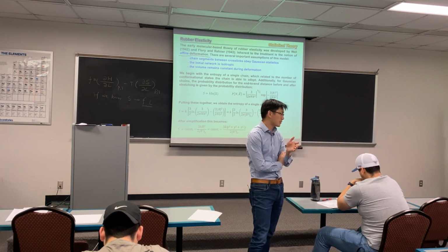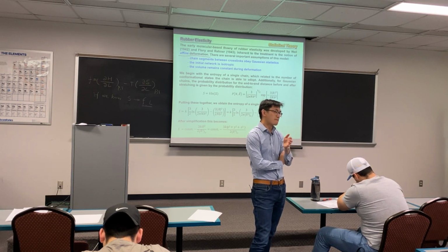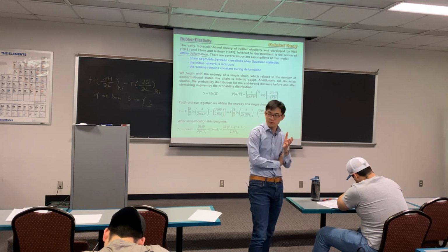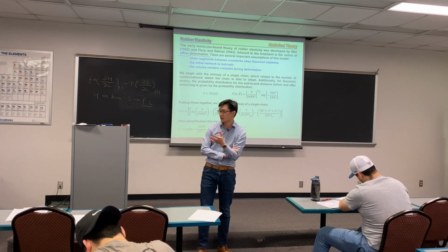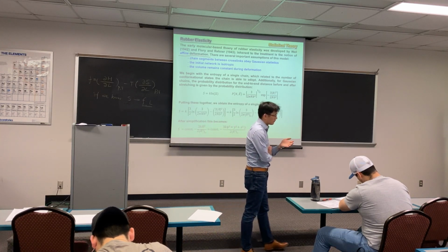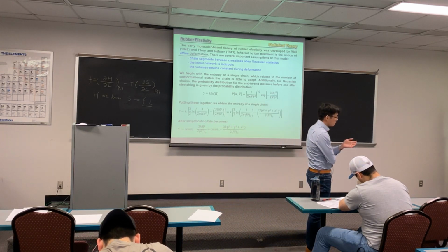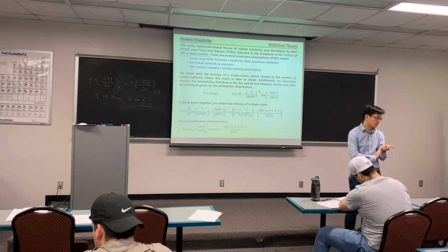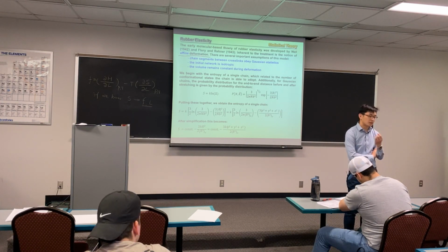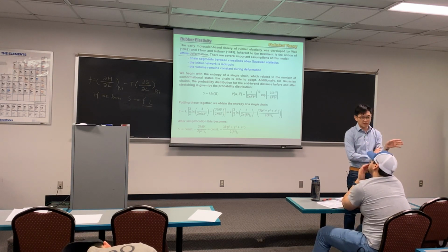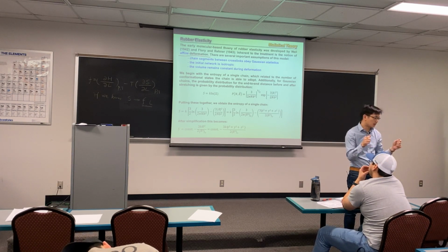Affine in this particular case is we are trying to link a molecular level change to a macroscopic level change. So let's say if you pull some kind of plastic, it would yield and form a neck. So your deformation is not uniform throughout the sample. Some areas are not deforming, but the necking area is being stretched a lot, right?